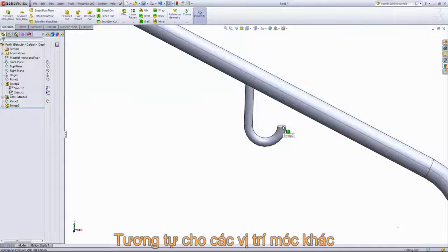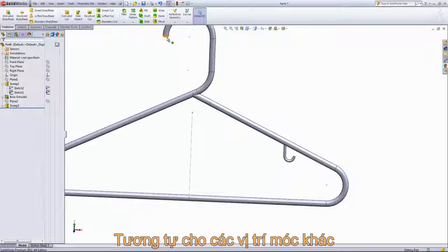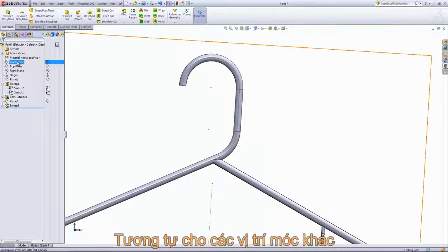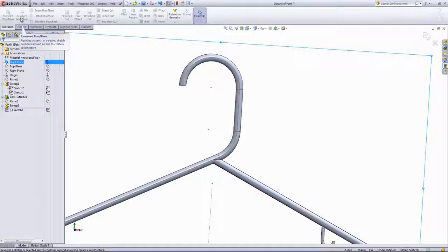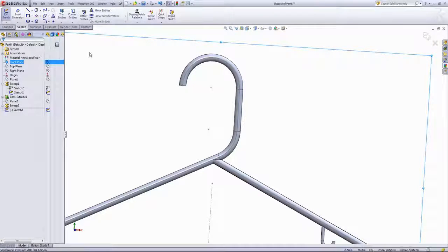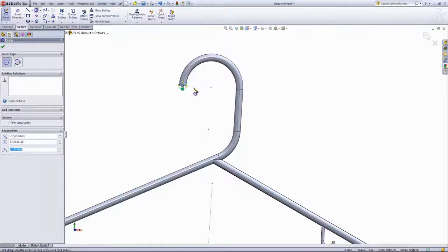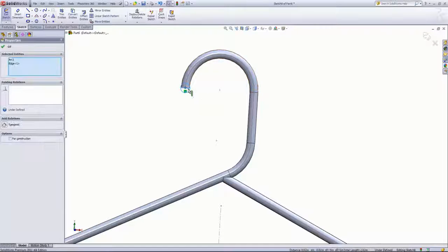The next thing we want to do is put rounded ends on both sweeps, the end of that hook there and the end of this top hook. And we'll start with that top hook. Next, I'll create a sketch on the front plane. And we're going to use a Revolve feature to actually create this cap. So we want to draw in a circle at this point and make it the same diameter as our edge there. I'm going to go ahead and make those two tangent.